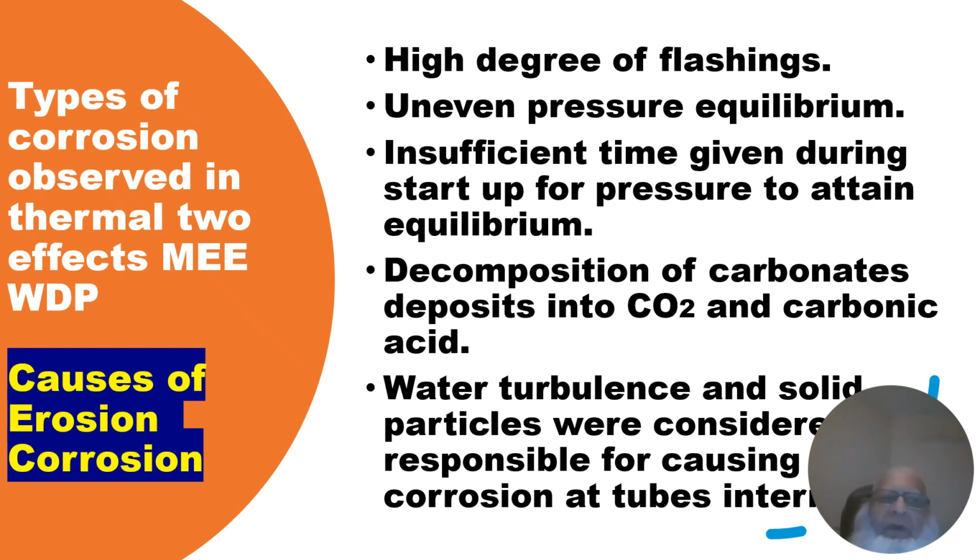Another was decomposition of carbonate deposits into carbon dioxide, forming carbonic acid. Water turbulence and solid particles were considered responsible for causing erosion corrosion at tube internals.